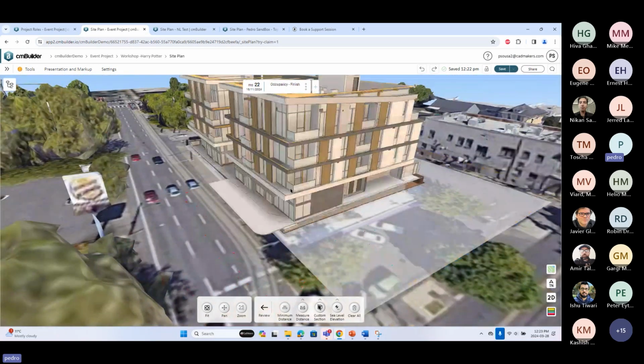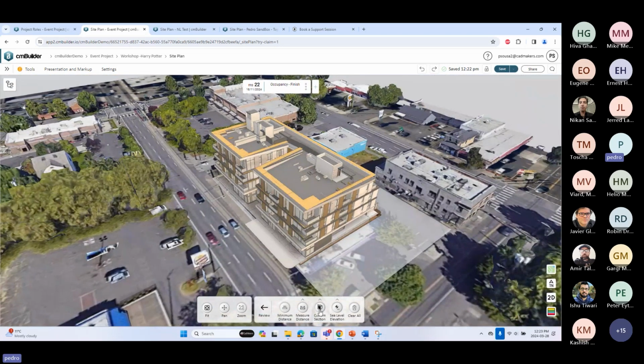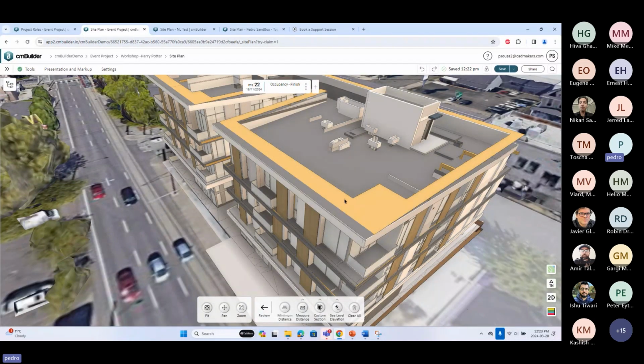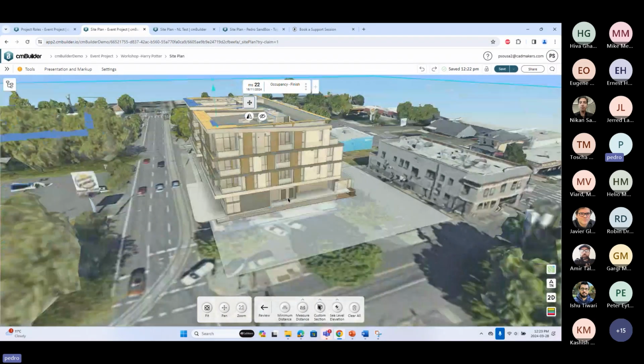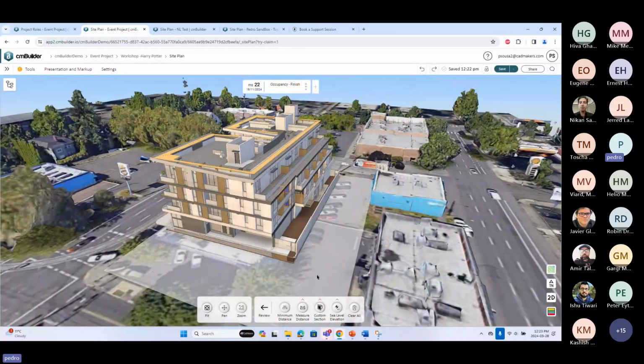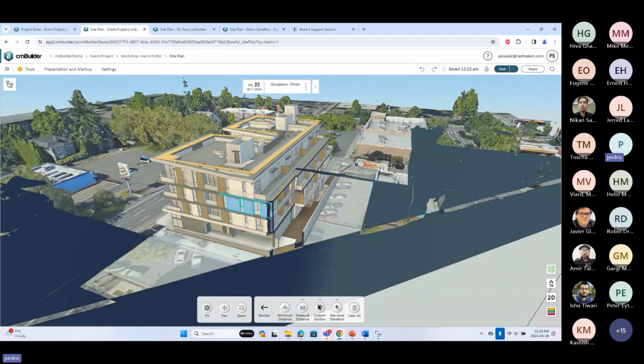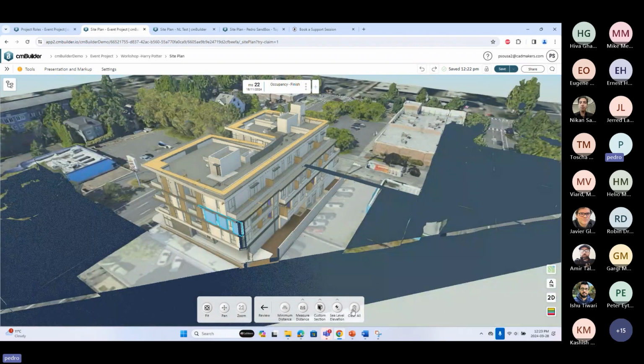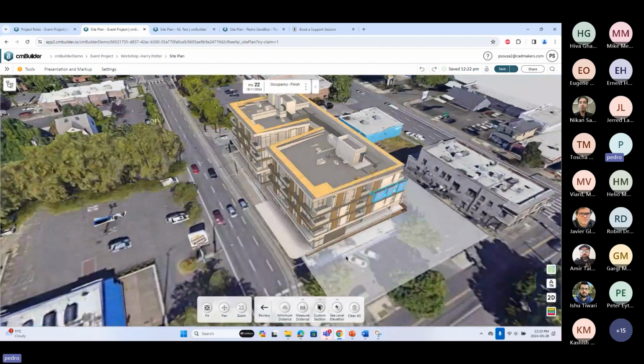And now let's go into the sectioning tool. The sectioning tool is over here in the bottom. If you click on custom section, you have to click on a known surface, so the software will align that sectioning with that surface. For example, if I click on the custom section and click on this wall, it's following that reference over there, and so on and so forth, right?